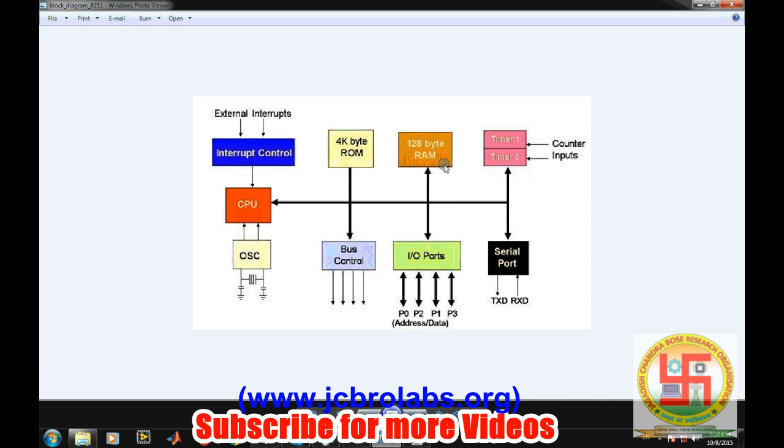Specifically, this 8051 microcontroller has 256 bytes of RAM. The 256 bytes of RAM are divided into two parts, a lower 128 bytes of RAM and an upper 128 bytes of RAM.